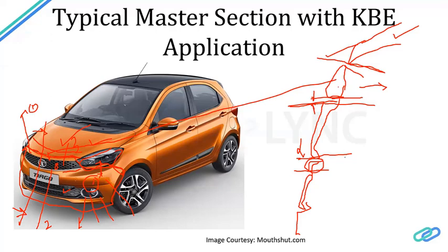Now going forward with the attachments. If there are two parts and the snaps are getting hooked into a different part, for example, if I have a snap here, and I want to use this snap in this part, the person who is working on this part will create the snap, as well as the interfacing geometry, which will go on to this part.